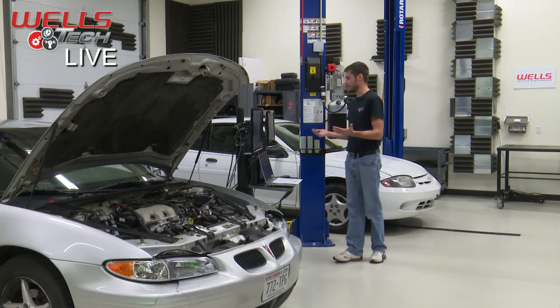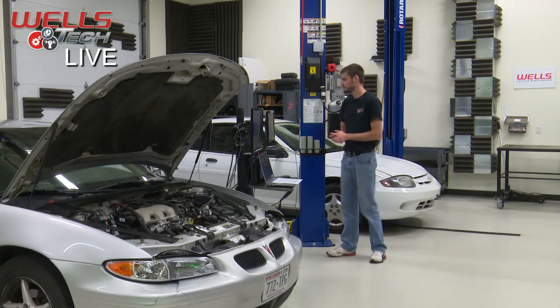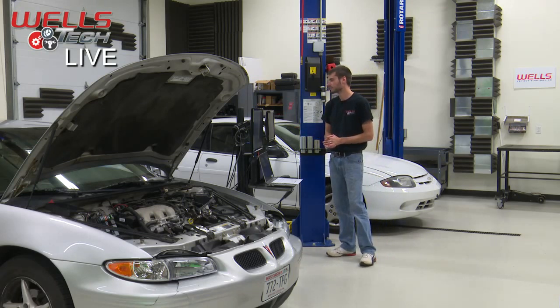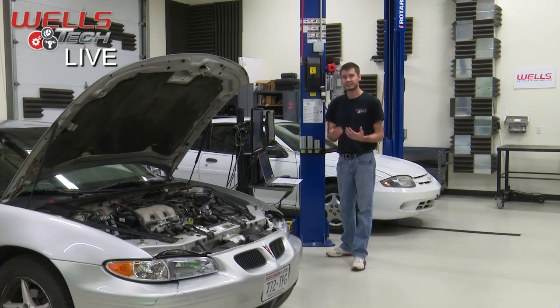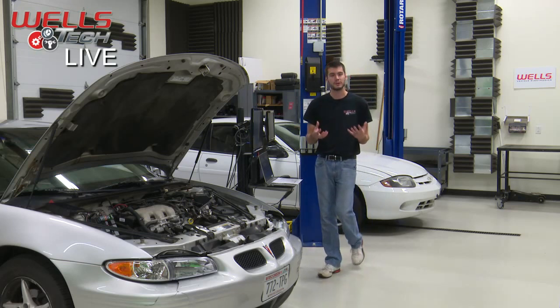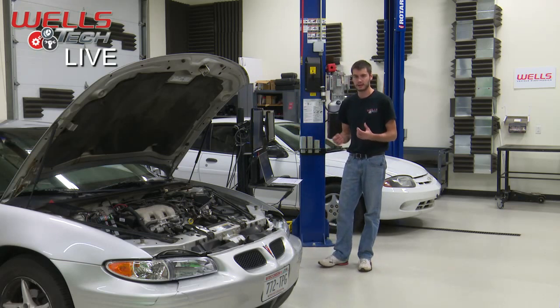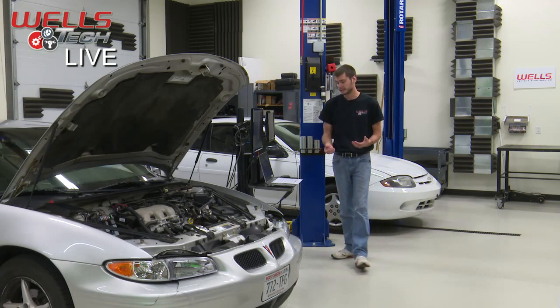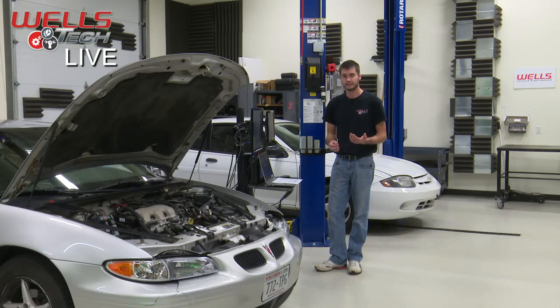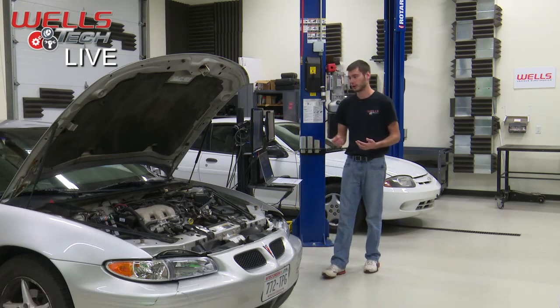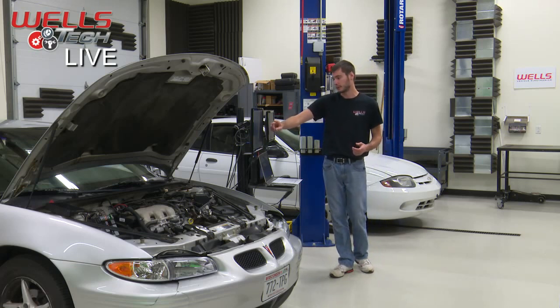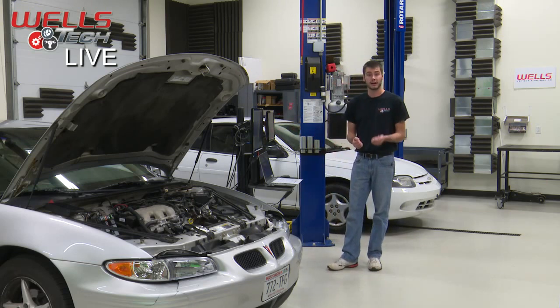It's going to change a little bit, right, Fritz? Yeah, most of the time you'll see it change a lot when you goose the engine. Okay, sure. So we might see some fluctuation out of that line, but it should be relatively steady, relatively straight. And what that's actually showing is that the cat is doing its job. That's right. This is actually signaling that the cat is not functioning right, but the sensor is warmed up and ready to work. If it wasn't warmed up, we would most likely see a flat line right around bias voltage of about 450.